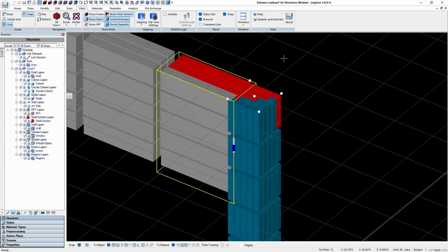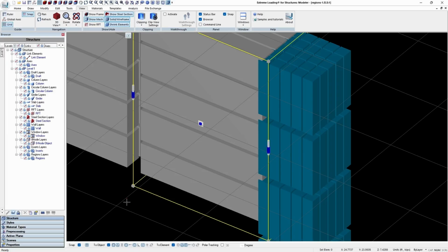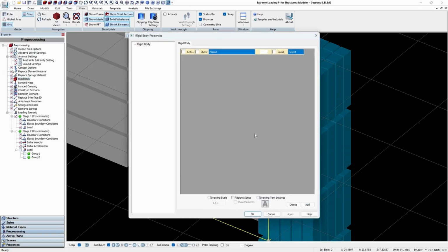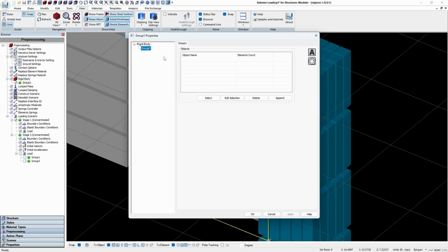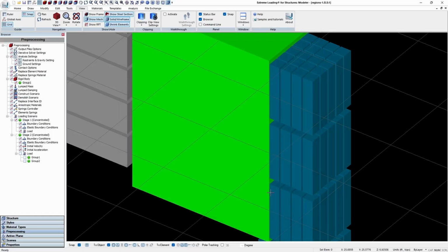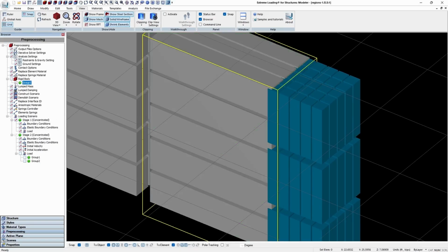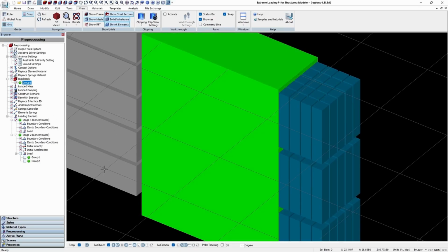While the use cases of the former methods may be self-evident, the regions over overlapped elements option may be used to later assign a rigid body to the region, and thus turn the elements within into a single element. This can make it easier to model complicated geometries or inclined structural components where overlapping elements might cause integrity issues.